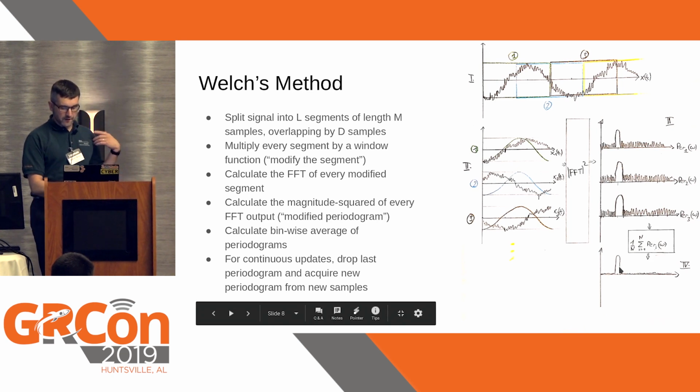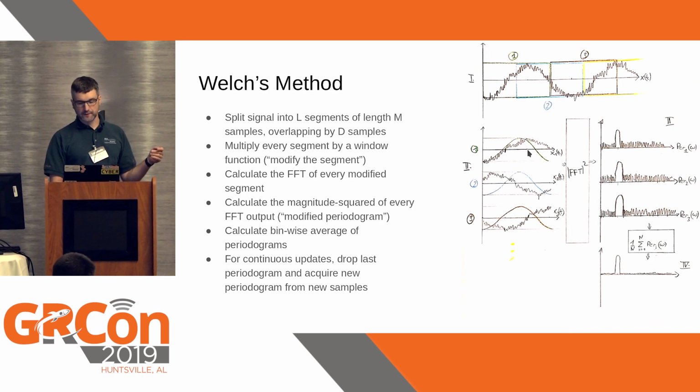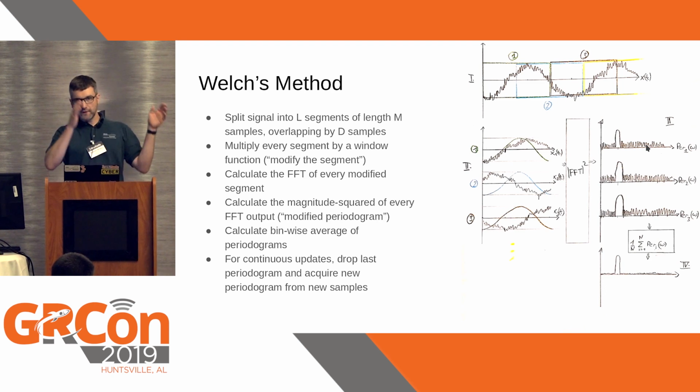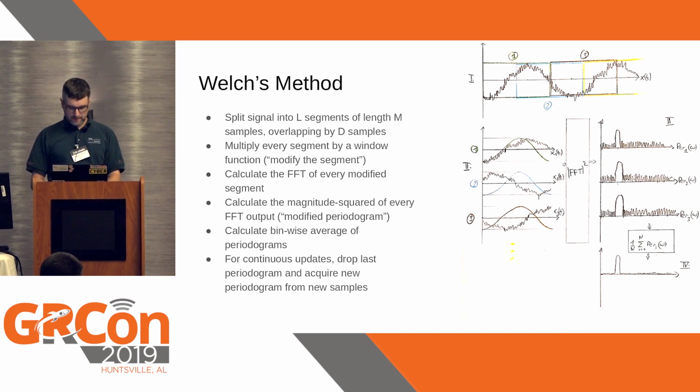And if you go back to my definition, you can find all the things that I mentioned in there earlier. Segmenting in time, so we can do F of t's. That's our time-limited Fourier transform. The modulus squared was actually in the definition of the power spectrum density, so I'm not even approximating anything here. And the more of these I take, the more I approximate t towards infinity. So there you go. And you can even do this in real time by saying, okay, I'm just going to limit this to, say, 32 averages. And then I'm always going to feed in a new F of t, drop the oldest one, and that's how I can do a continuous update of my spectral estimates. So that's a way of doing spectral estimation.